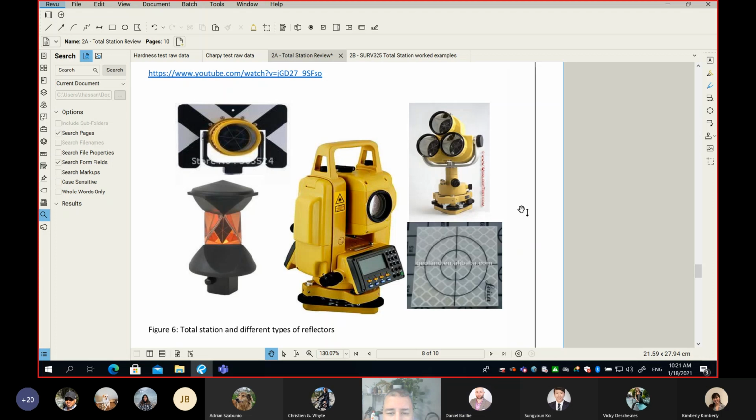Exactly, sir. So here is the point, and that's the point I'm trying to make here. Although this one on the right is very, very accurate for being above the point, it is used only for the control network, for the traverse points. However, once we start our survey to locate some points in space, like building corners and trees and stuff like that, we do not use a tripod, rather we use a single prism on top of a rod. I know maybe at SATE, we don't do that, only for the sake of time, because it takes a very long time to do that.